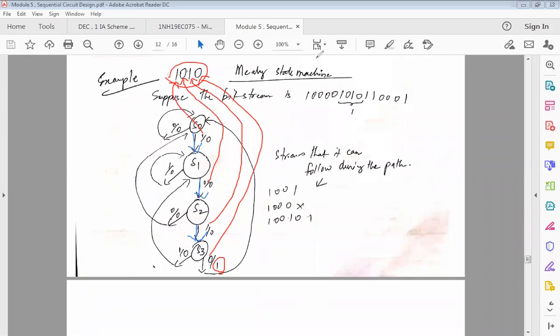Now let us go with the other case. As I told you, we have 2 cases, which are 1 and 0. Here when it is 1, it is moving to the next state. So when it is 0, what is my first bit here? The first bit is 1. So when it is 0, there's no point in me going to the next state, because it means that I have not detected my input. So I will go and sit in the same state till I get 1. Which means 0 means I will be in the same state. Only if it's 1, it moves from S0 to S1. If I get a 1, then it means this bit is done. Getting my point? All of you are understanding what I'm trying to say? Yes, sir. Okay, good.